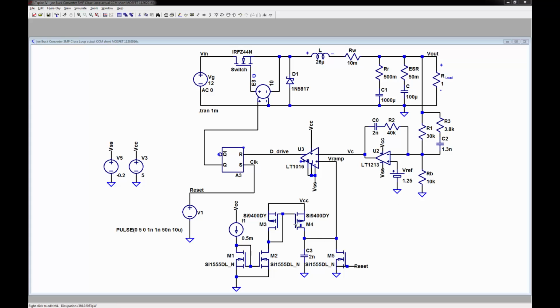Now, why don't I put this constant current source right here? Because this is an ideal current source, and you want the parasitic stuff, and it'll act very strangely to a short and an open. It doesn't like the current source to be here directly. So this is a simple current mirror. You could see that this is tied to here.